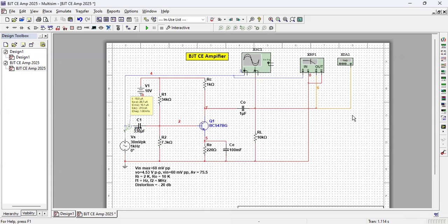Now, this is an amplifier that we have designed. Purposefully, we targeted to make an audio amplifier. And as I said repeatedly, audio signal is always tested at 1 kilohertz. But for an actual signal, when somebody speaks, normally the lowest frequency is around 200 or 256 hertz, and the highest frequency is maximum around 3 kilohertz. But for the sake of theoretical calculation, for the lowest frequency you can take 100 hertz so that your amplifier is always good.